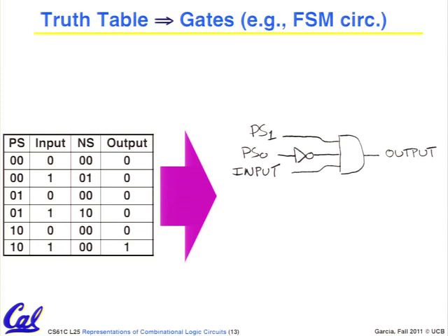Isn't that nice? So if you ever want to have a circuit that goes high when an exact bit pattern is true, just flip all the guys that are zeros with these little mini inverter guys, pass it into an AND gate, and it'll only register high when that exact bit pattern is the case. Isn't that kind of neat?